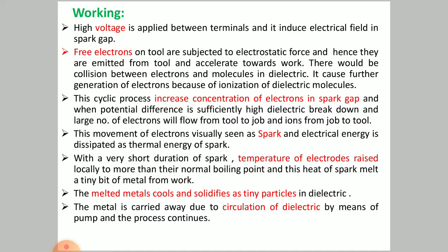This principle is utilized in the electro discharge machining process. High voltage power supply is given to the workpiece, and to the tool, which we observe negative terminal is given. But here we are maintaining the gap between workpiece and the tool, due to which the spark will take place, and in controlled parameters in the presence of the dielectric fluid, the dissociation of atoms, dissociation of ions will take place, right?